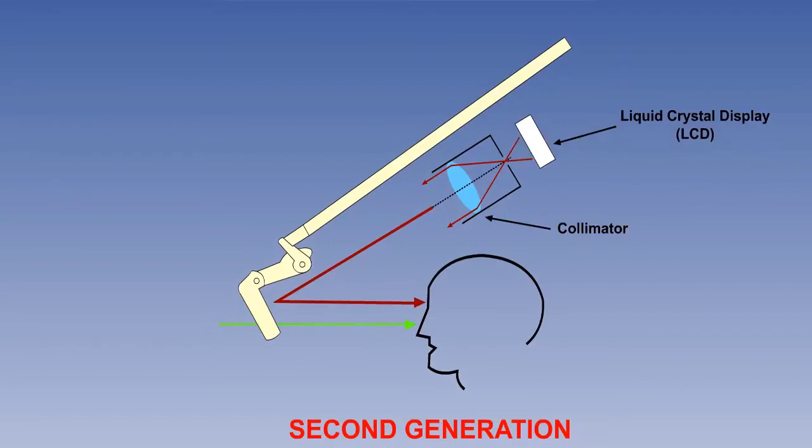Second-generation systems replace the cathode ray tube by a solid-state light source, such as a liquid crystal display. This saves weight and does not need high voltages, thereby avoiding unwanted heat generation. It also largely overcomes the fade problem. These too are in current aircraft.